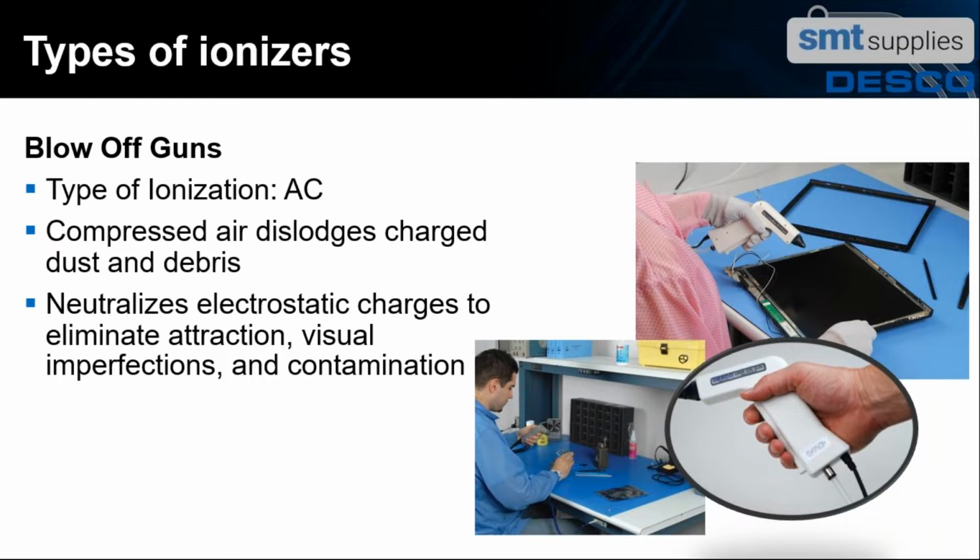One thing worth noting is that if you have a regular air gun and the air going through that gun is clean, that air won't generate a charge on anything. The reason for that is the air molecules are so small that when they have contact and separation with the surface, they don't create enough static.